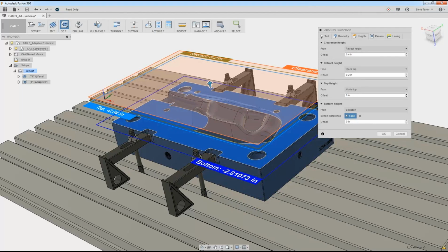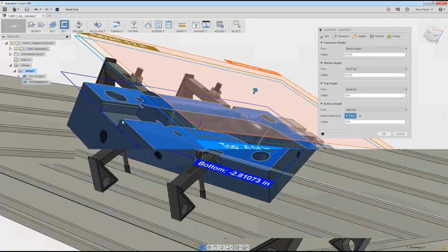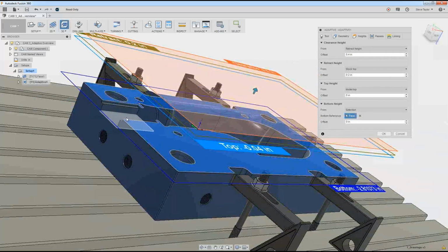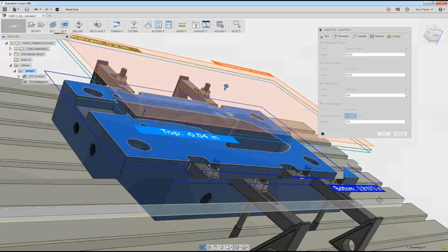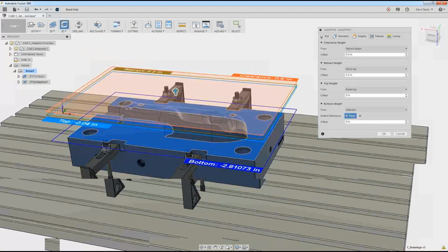At this stage, we're forgetting about this end section that goes below the face. So as we're looking at this now, I'm forgetting about this little section here, because we're going to come back and do that in a 2D roughing strategy. This is going to be our 3D adaptive one, just as we're there. We can then go to the passes tab.